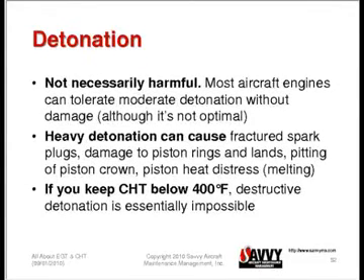Now, detonation is not one of these binary things. It's not a question of either being in detonation or not. Detonation comes in all flavors, from mild to heavy. Mild detonation, or even moderate detonation, is normally not enough to damage the engine, although it's certainly not optimal to have instability in the combustion event. But we get these engines into mild detonation without doing any harm. In fact, mild detonation just keeps everything real clean.